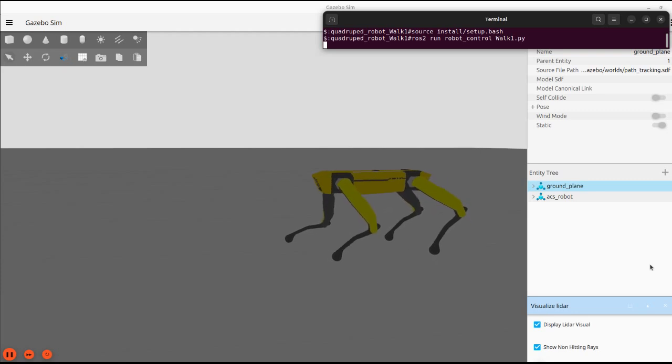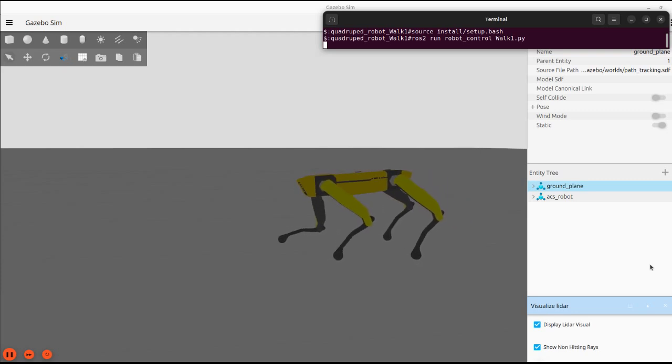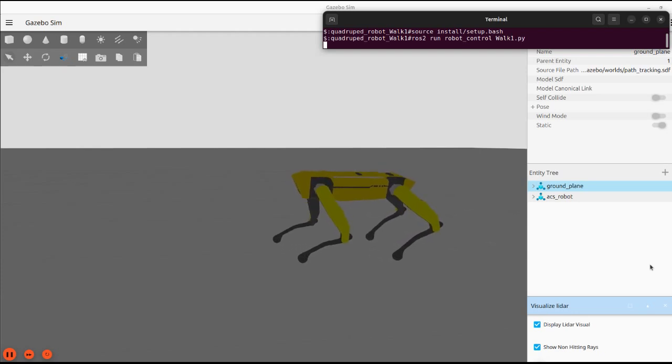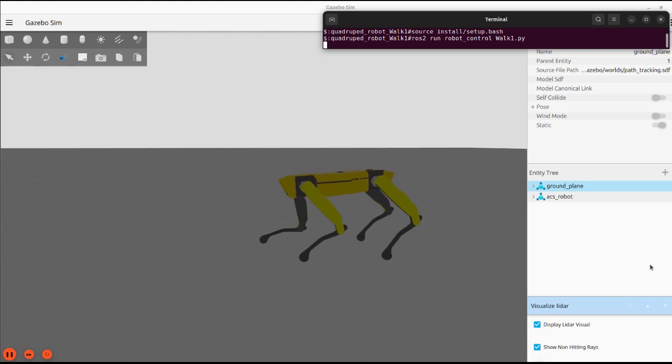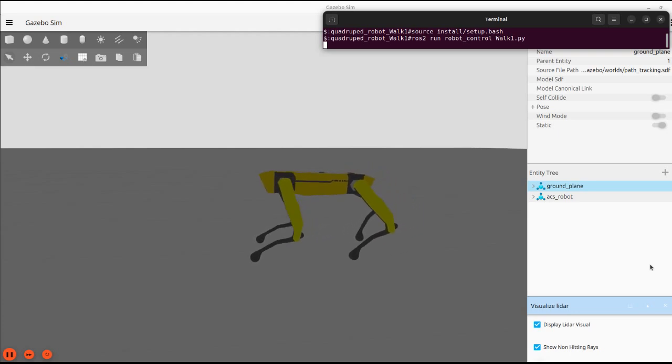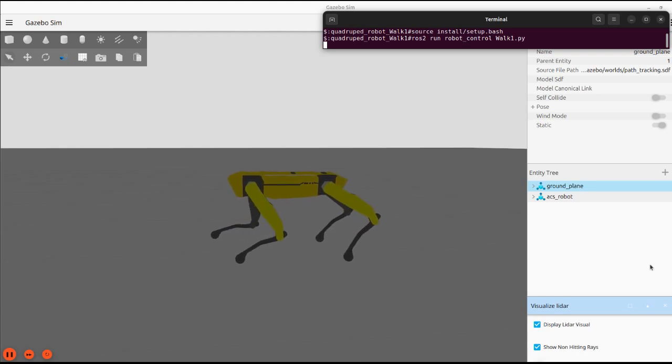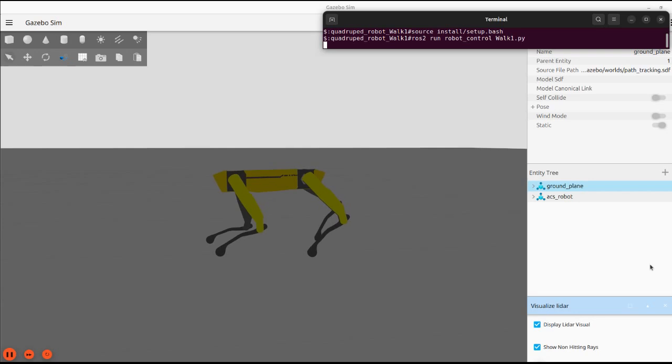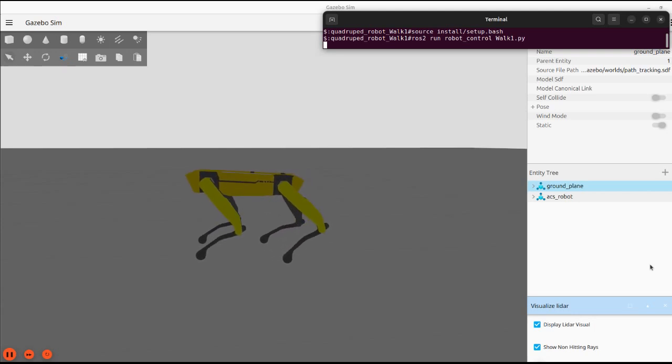Robot tries to extend his front legs as far as possible. It also lowers its front part of the body to enable larger step by back legs. As was discussed previously, in walk 1 program, robot repeats same walking sequence twice.